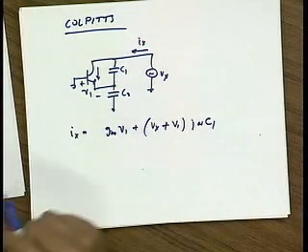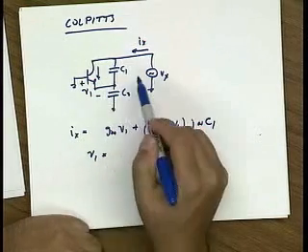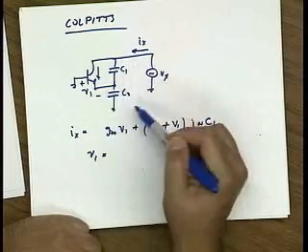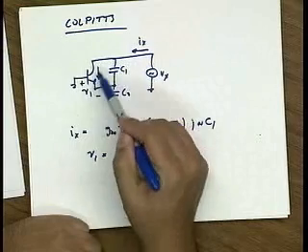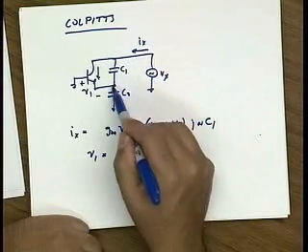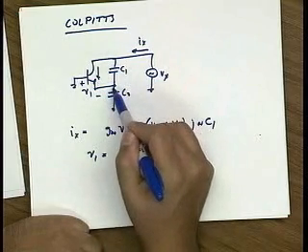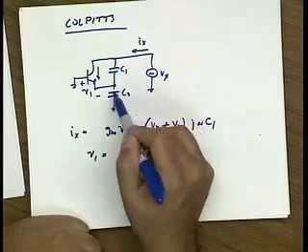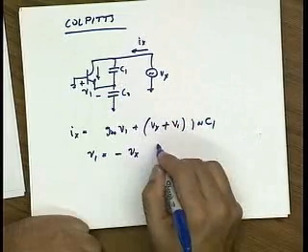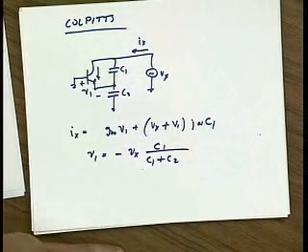Well, what's V1? V1 is this voltage, and if we assume that in resonance most of the current is flowing through this capacitor, in other words, the transistor contribution is small, if we neglect the loading here, then the voltage V1 is basically minus the voltage Vx times the divider C1 over C1 plus C2. Okay.